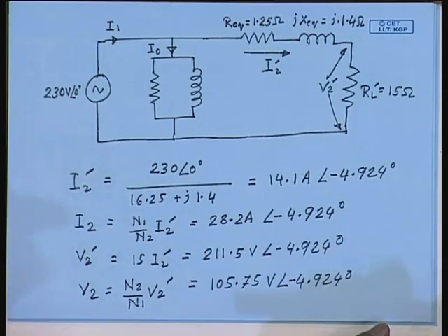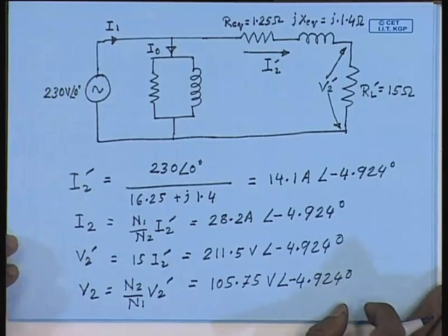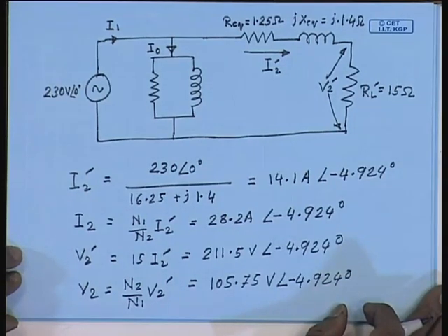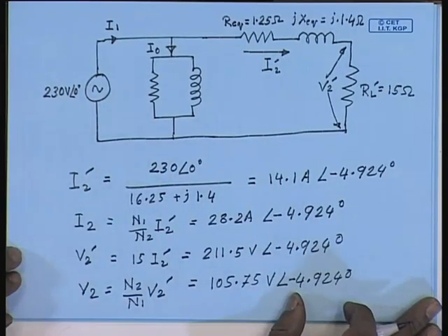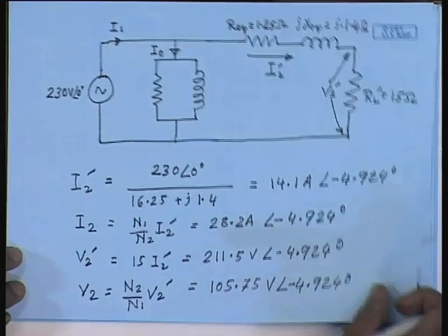The simplification in the calculation is very apparent. We do not have to find out the Thevenin equivalent voltage or Thevenin impedance, we can simply calculate the variables. I0 and I1 can be computed similarly.